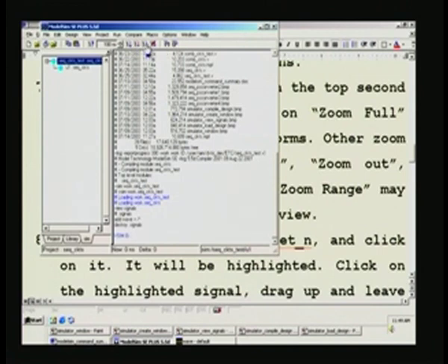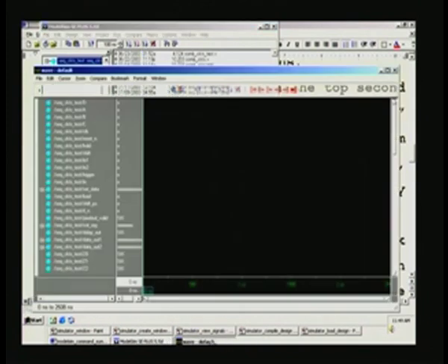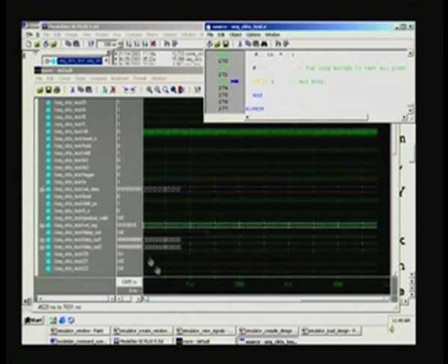Here it says run here, followed by continue to run, and this one is run all. If you give this run all, then it will start running. You also had a wave file opened already here, and here also you have the very same thing. For example, if I click this run all here, it will run, and you can spontaneously see the waveforms right on the screen. So I will click on this, let us see what happens. You see the whole thing become alive with waveforms here, and it also opened your source file, that is the test bench, sequential circuits underscore test.